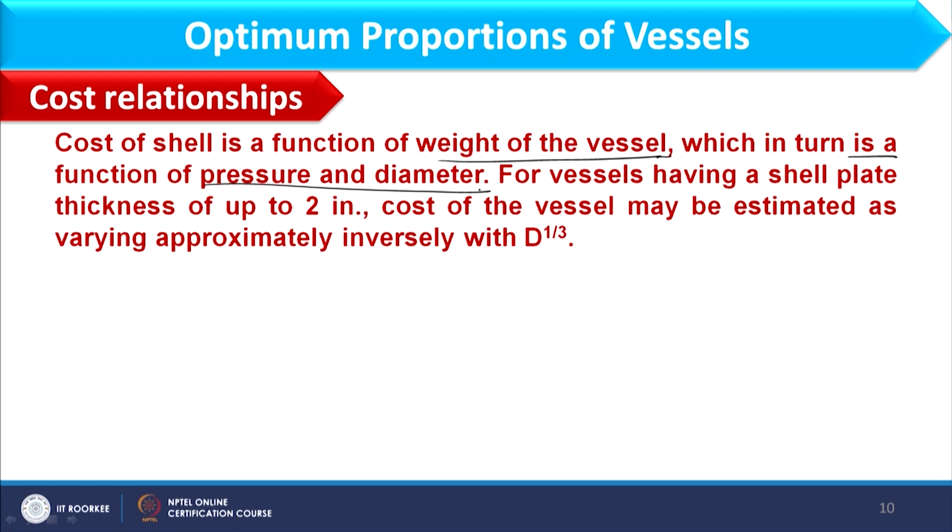Now, why is it a function of pressure? Because based on pressure we can find what should be the thickness of the vessel. So, pressure will play its role in computing the thickness, because based on thickness as well as diameter I will come to know how much material will be required.